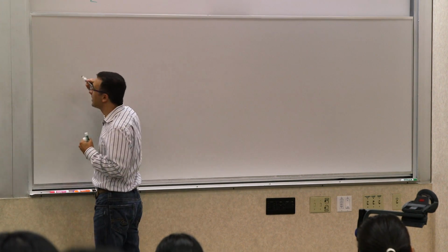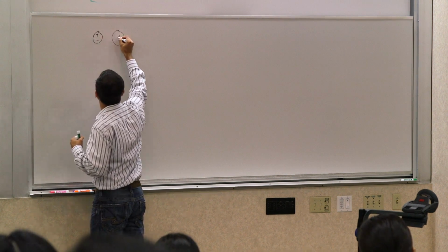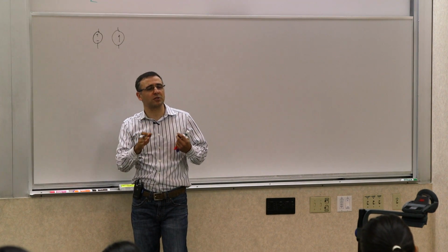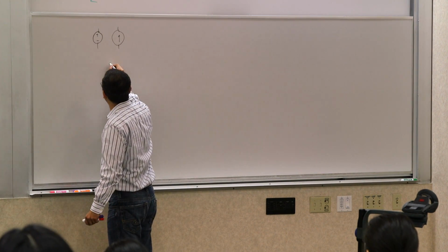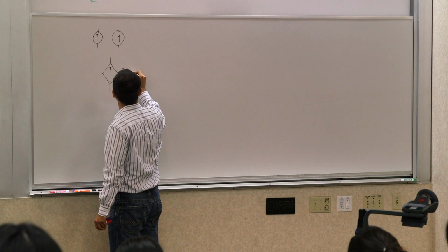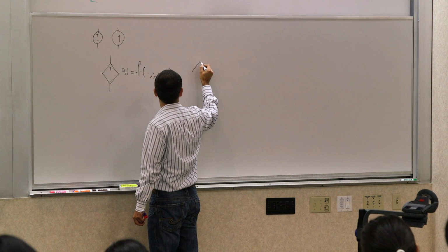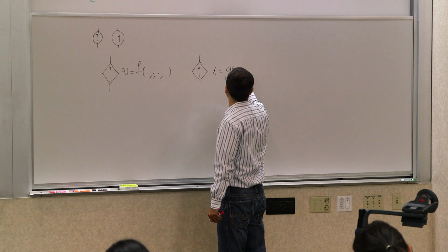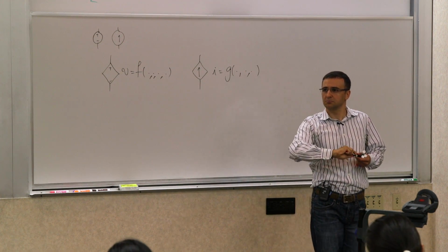The dependent sources. Independent sources we are showing with these circles, right? The voltage or current, etc. There are also dependent sources, what we call a source whose voltage or current is a function of other voltages and currents in the circuit. So you can have a dependent voltage source, and we show them with these diamonds, essentially, where the voltage is a function of some other voltages and currents in the circuit. Or it could be a dependent current source, shown like this, where the current is a function of some other parameter, some other voltages and currents in the circuit.